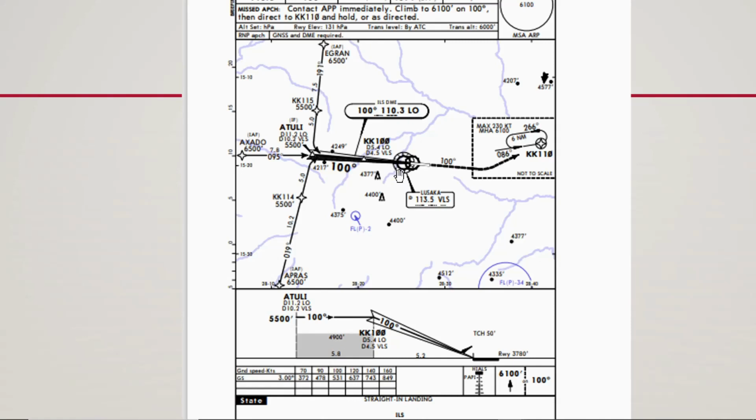So a quick review again, just a quick one. I'm not going to go through the whole ILS plate here. This is the subject of another lesson, which I should be making another video of in the coming days. The localizer is this one, as I've said. Always on the plan view you have the localizer fan, and how you know it's a localizer fan is that the right-hand lobe is always shaded in gray or a darker color than the left-hand lobe.